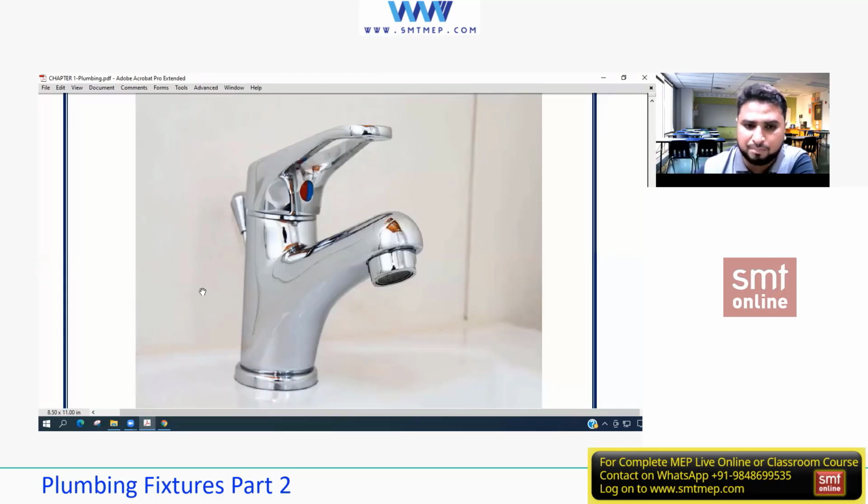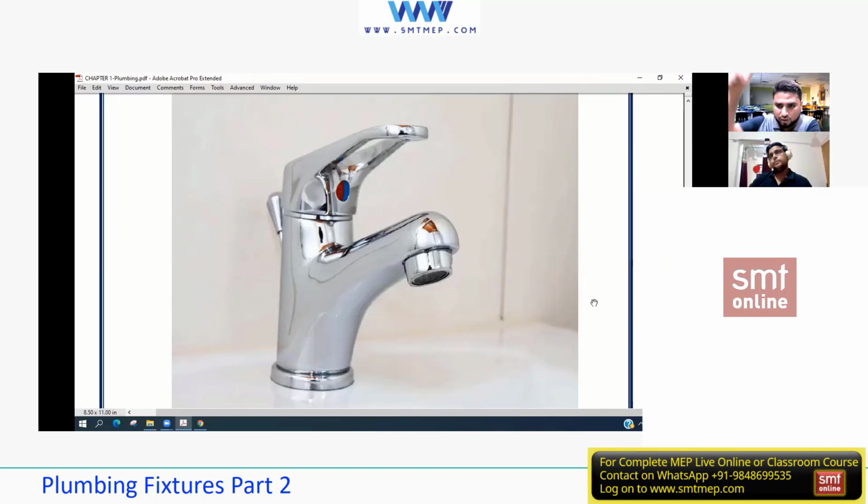If the main pipe is of 3 inches or 4 inches, what do you people think? As the water comes down, the gravity pressure also adds up. Yes or no? So around 10 kg pressure, and as it comes down, it increases more and more. And we know that every fixture demands a certain amount of water and a certain amount of pressure, not more and not less.